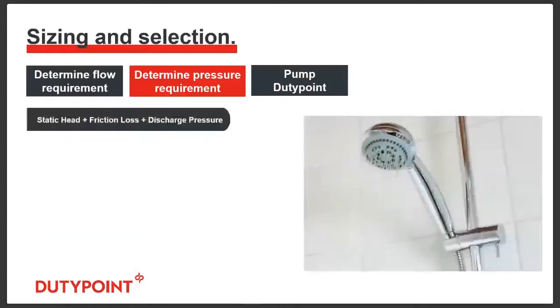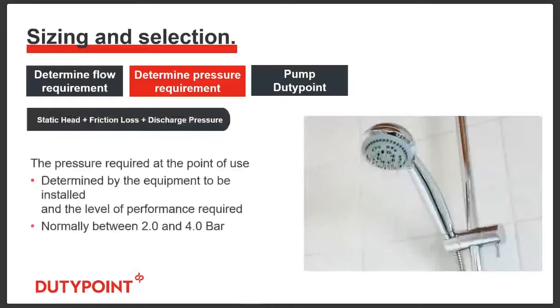And then take into account the requirements of the installed equipment. So typically between 2 and 4 bar is what you need at the other end. 2.5 bar is normally sufficient.